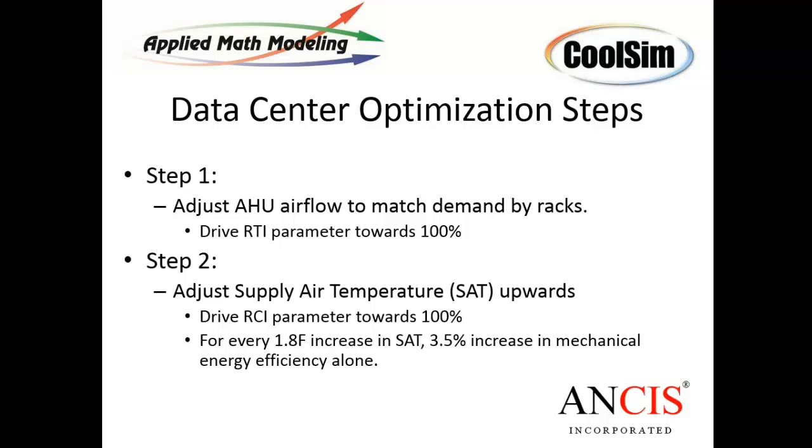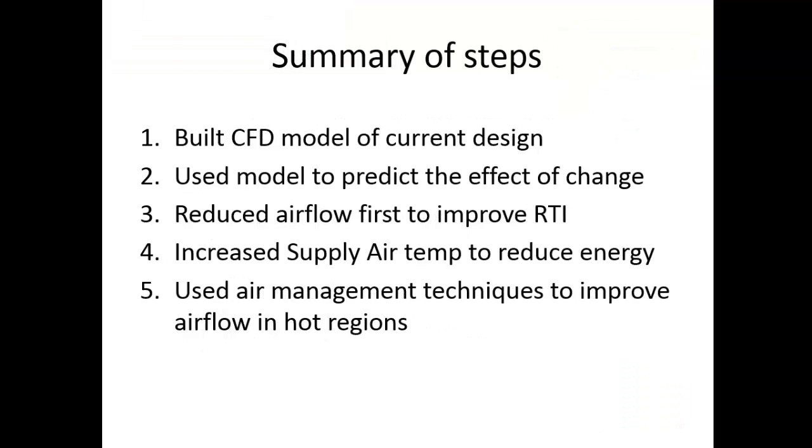Rule of thumb, generally people say, for every degree F, you get a percent increase in your mechanical efficiency. It's actually, as you can see, a little better than that, depending on the situation. And as Magnus pointed out, if you've got any kind of economizer here, whether it's air side, water side, if you can increase supply air temperature, the window of opportunity for using outside air to cool your data center, either directly or indirectly, goes up tremendously. And that reduces your energy by a significant amount. So raising supply air temp is important for a couple different reasons.